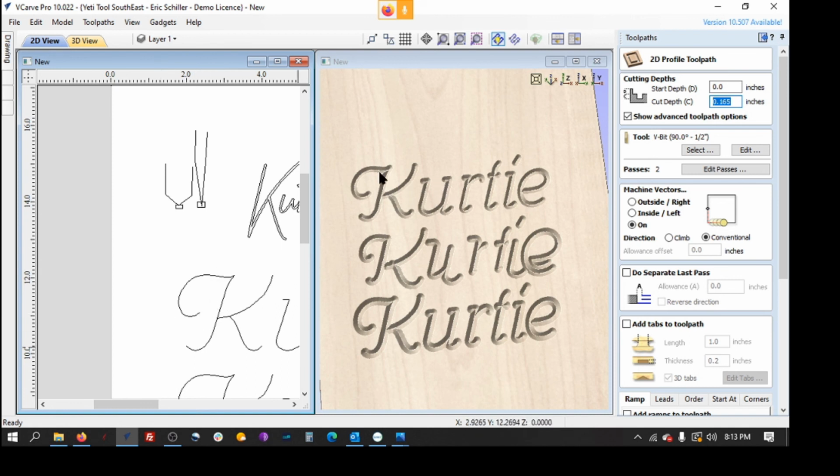But you see the difference between a 0.125 and a 0.145 and a 0.165. So that's 40 thousandths of a difference between here and here. It's not much. That's less than 3/64ths of an inch. The guys that work in metric, yeah, it's a little easier to understand. But this shows the difference in what we're doing here. So that should help clean him up.